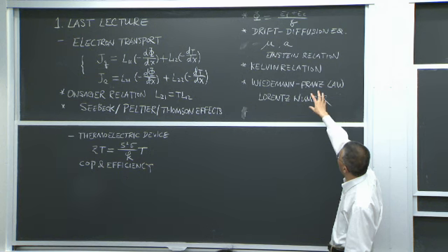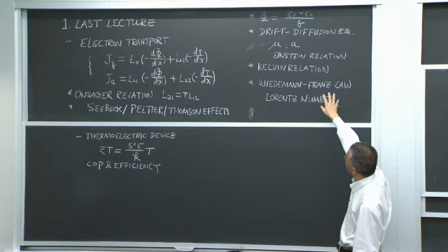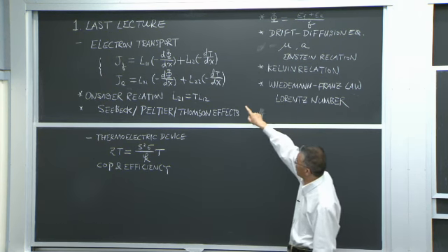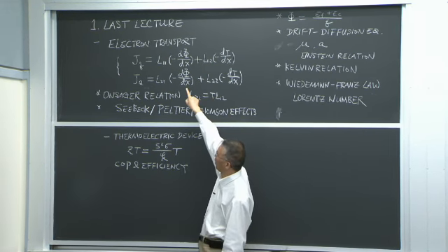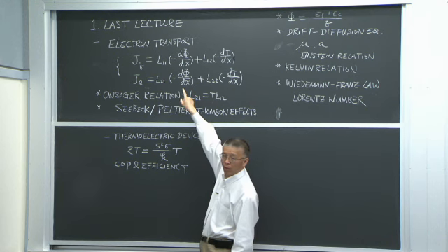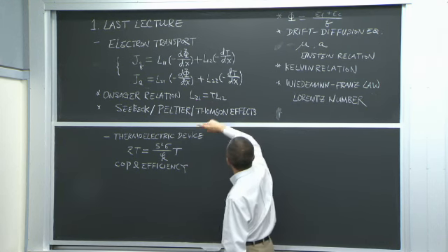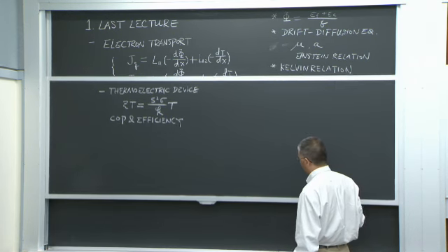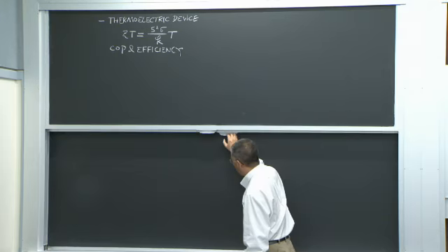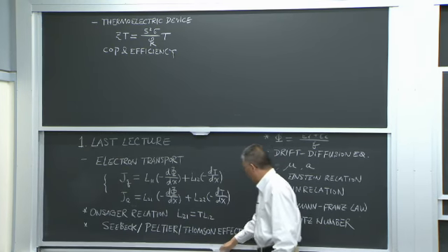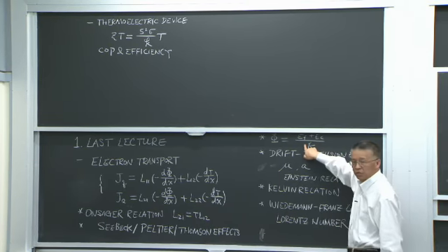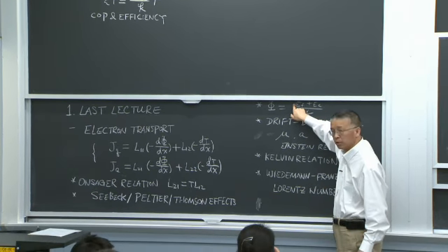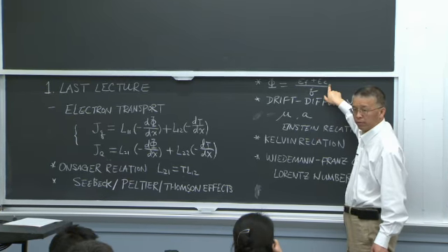We also have in electrical engineering, say, the drift diffusion equation, which is actually just the first term of that JQ. L11 is electric conductivity, and then when you write it into the separate expression, we split out the driving force for the current flow, which is the electrochemical potential. It includes the chemical potential and electrostatic potential.